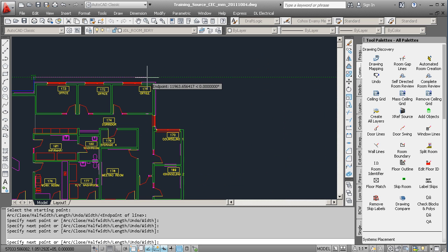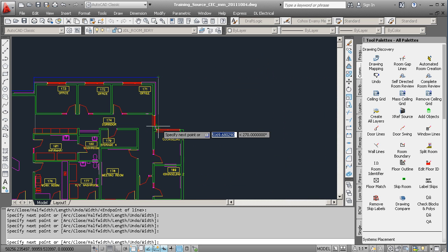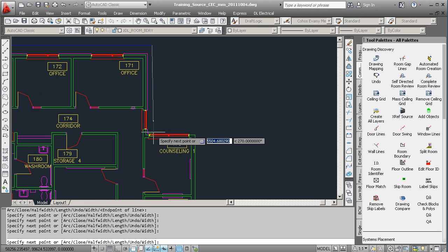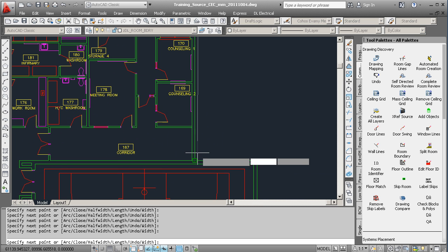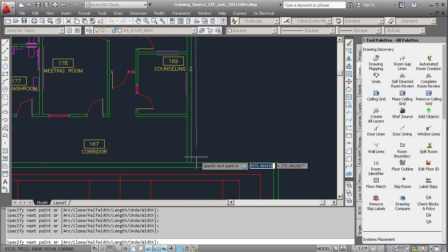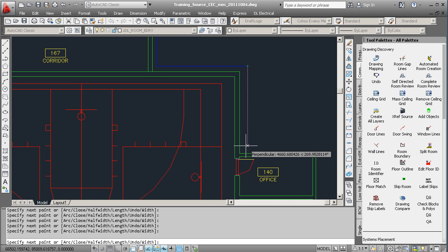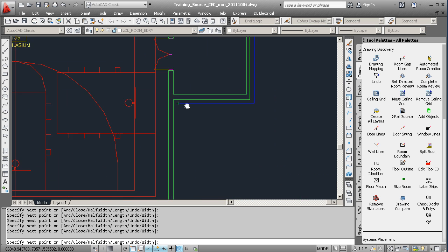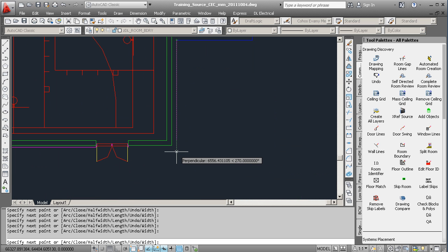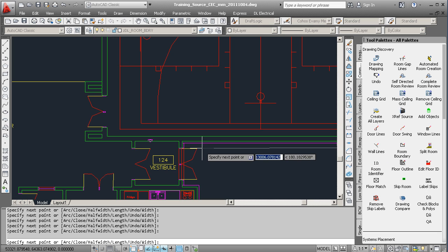And you must leave enough room at least for the insertion point of any exterior devices. So if you're going to have any exterior plugs or lights, you want to leave just a little bit of room so that you can have those devices on the exterior of the building and still have their insertion point, not necessarily the whole block, but at least their insertion point within the floor boundary for the floor that they belong to. You may also want to leave room for any exterior parking lots in case you're going to have plugs for those winter climates.